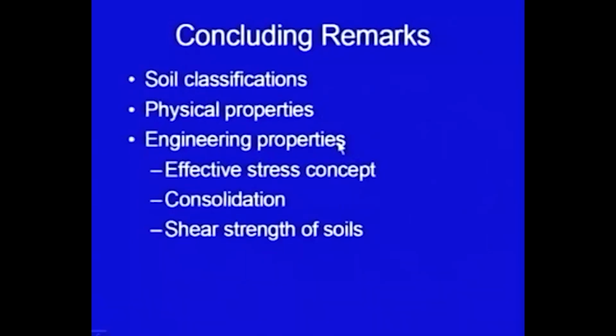Then I touched on the engineering properties in brief. The very important concept, the effective stress concept, has been discussed. Wherever applicable, we will use this concept. Please remember, wherever you want to find out the strength, you have to use the effective shear strength parameters and the effective normal stress.